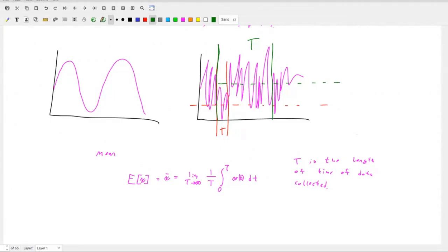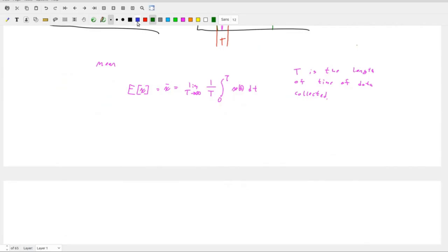Therefore, for a signal not centered around 0, we can obtain a 0-centered signal, or we want to obtain a 0-centered signal, right? So often we're just going to subtract the mean out of our signal. That's super easy to do. We're just going to call that x prime of t, back in our time domain, equal to x of t minus, let's just go with the x bar notation, x bar, right? So this gives us a signal centered around 0. So we're no longer off-centered if we need to be.